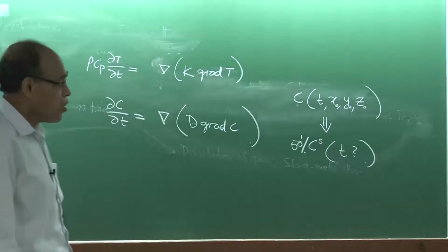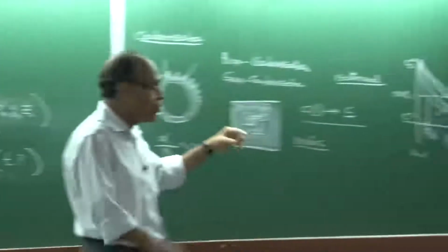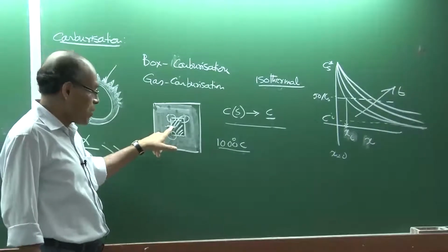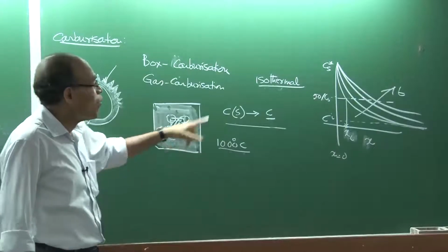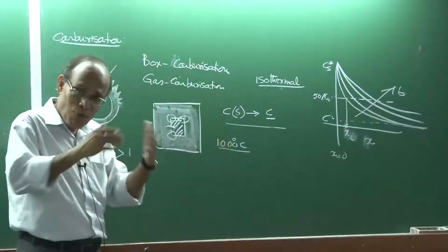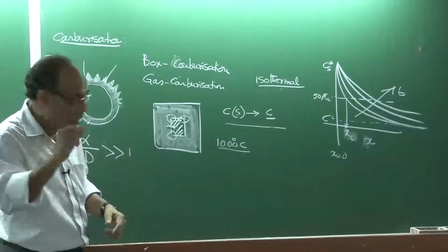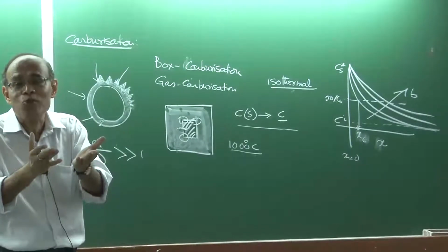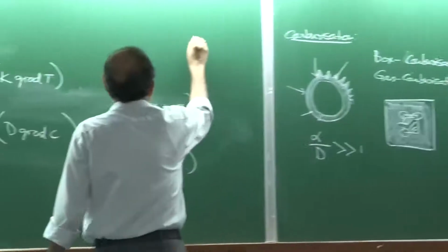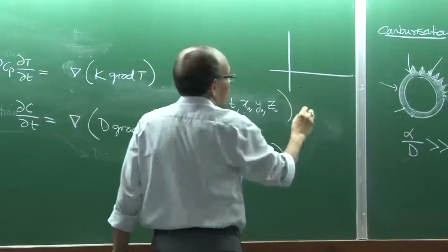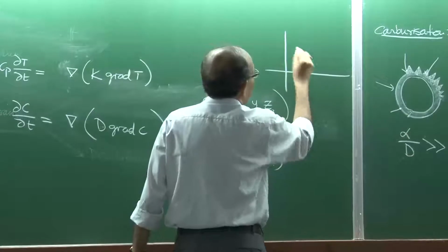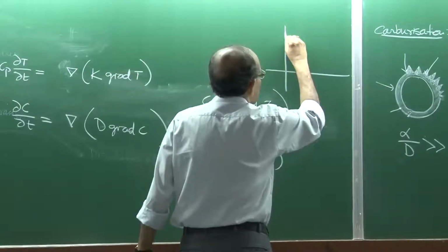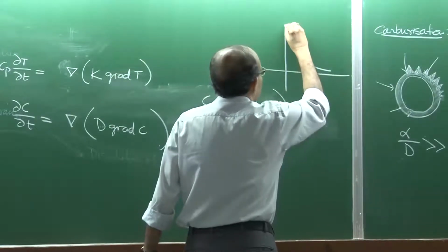By applying the boundary condition. So if you want to do it in the laboratory, what you basically do is take a long strip, measure at this particular point, and apply the one-dimensional theory, which means the error function solution. From the error function solution, you can calculate the time, then take out the sample at that particular time, observe it under a microscope, and compare. If you do it at different temperatures, you can measure the carbon concentration.